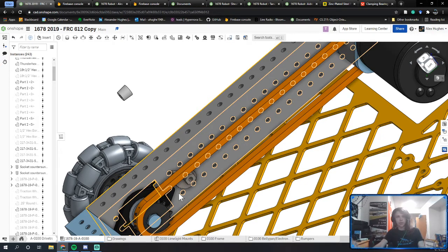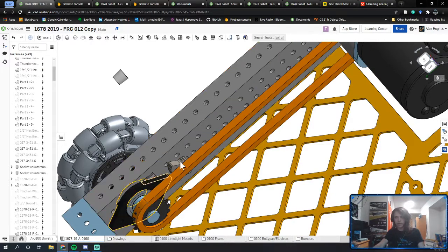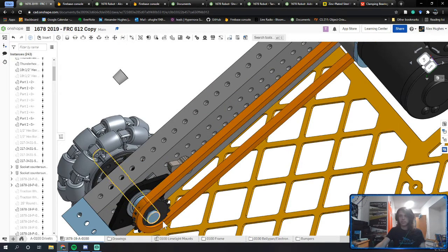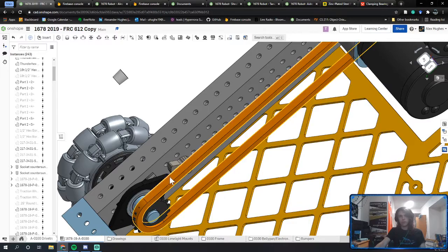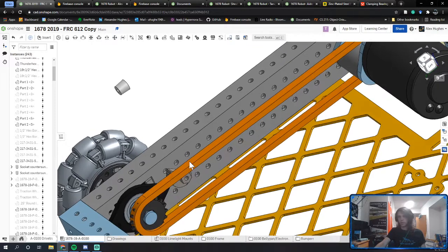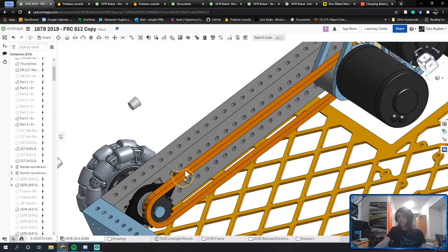If you ever design a drivetrain and you have long belt runs or chain runs, you always need a tensioning system, because it might work at the beginning of the season. You might design this and it'll work great, but then when you get to district championships, your robot is going to start having skipping issues and other problems, unless you actually go in there and replace the chain, and that's just a whole ordeal. It just wastes time. The great thing about this is you can just twist it at the beginning of every competition. You just make sure it's tight, and you're good to go.